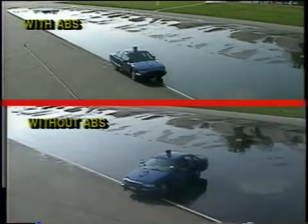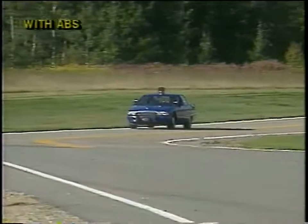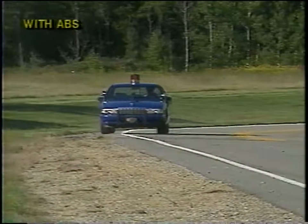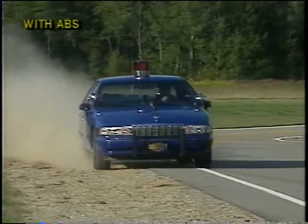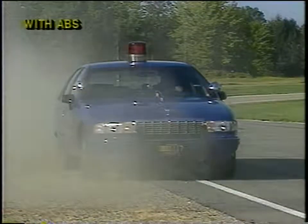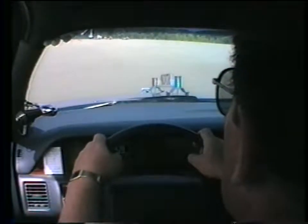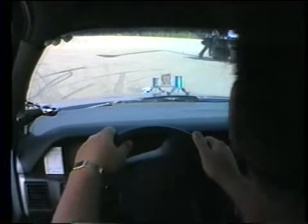An example of this in the field is stopping half on a gravel shoulder and half on pavement. The vehicle speed is 60 miles per hour. We did not attempt this stop without the aid of ABS. As you've seen, ABS improves the officer's ability to better control the vehicle during hard braking situations by providing improved steering control and, in many cases, shorter stopping distances.